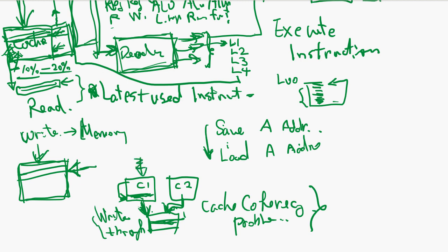But in general programming, you don't know when you're going to modify that data in the cache. So what you do is, when you use a cache and you write the data, eventually this cache becomes full. So there is an independent state machine for the write cache, monitoring the situation.